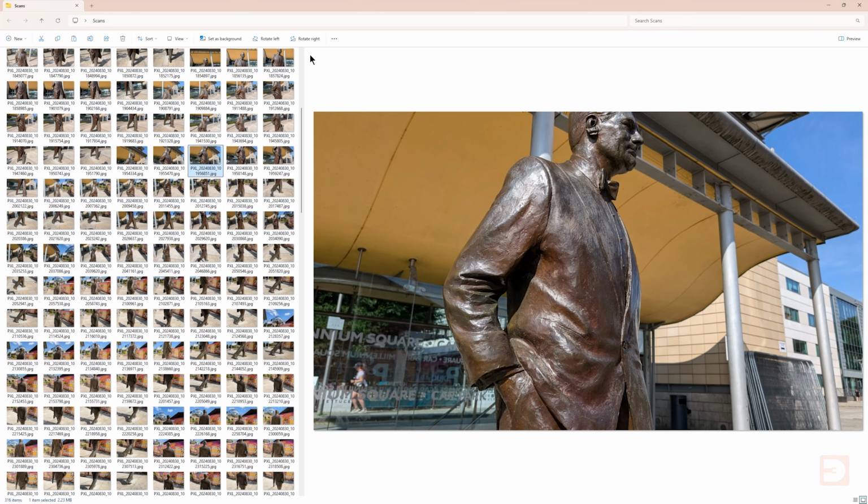Once you've taken all your photos, before you throw them into your photogrammetry software of choice, you'll want to quickly go through them and assess them, deleting any that are blurry or otherwise unusable. Whilst at this point it might be tempting to crop some images, undistort them or run them through an AI upscaler, none of this is recommended for photogrammetry. AI upscalers create new information, and whilst it's an educated guess, it's still a guess. So it's going to create new information which is completely different for every photo, and that will confuse the software.